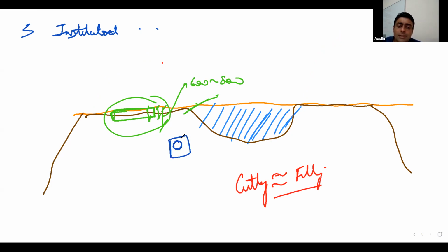when they were asked to provide service lines, let us say this was a sewerage line. Now, generally, the sewerage line flows under gravity, isn't it? Now, because they had cut so much, further cutting meant that they had to do a lot of blasting, because already they had cut 6, 7, 8 meters. Once you have cut this much, you naturally encounter very hard strata, which could not be cut with drills or hammers. You just had to use blasting. So just to provide their service lines, sewerage lines, water supply lines, which all generally function under gravity, they had to go for much more blasting and much more cutting, isn't it?